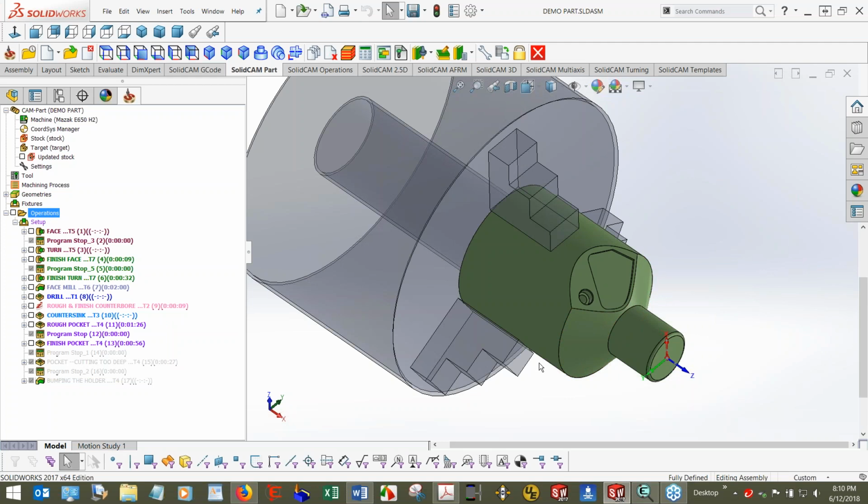I've got one up, and in here I'm using this chuck as my fixturing. It's inside the machine. It just depends on what size of part we're running, whether a 2-foot chuck, an 8-inch chuck, or a 12-inch chuck. What I like to do, as Ken's talked about, is get a green light in SolidCAM, and everything should be good in there. If it's all good, then we send it out to Eureka to do our final verification. So make this like 2 green lights and then send it out to the machine.